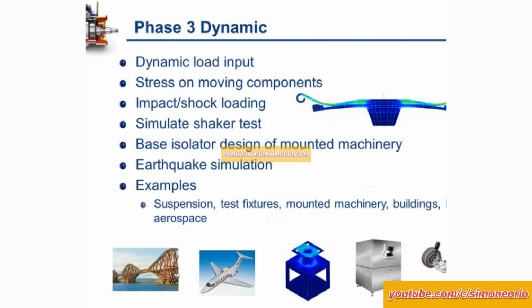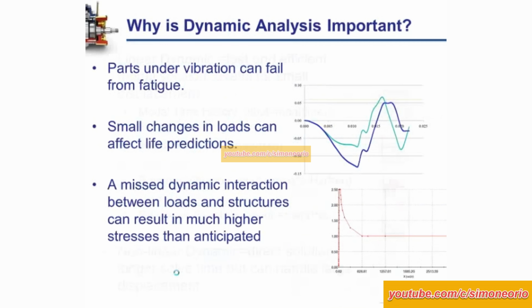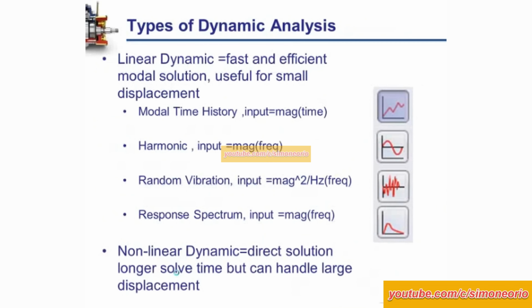So let's jump back over and take a look at these dynamic studies. In this case, we're doing the drop test, and then we're also doing a nonlinear dynamic study. We also have linear dynamic solutions, and these are pretty much going to emulate what's happening on the shaker table. So if you do take your products and ship them out for physical testing, where they shake them, the harmonic analysis and/or the random vibration are usually the types of frequency sweeps that people run dynamically. That is an option in addition to the time impulse that we're going to look at.